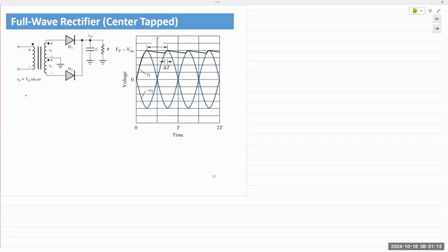And I believe this is also something they would have seen in magnetic circuits, right? So I still remember when I was a student, we had variable power supplies. And those variable power supplies would have multiple tappings in the secondary coil. Each one of those would result in a different voltage, like 1.5 volts, 3 volts, 6, 9, 12, 15 volts. And so depending on where you're tapping the secondary coil, the amount of voltage that appears changes.